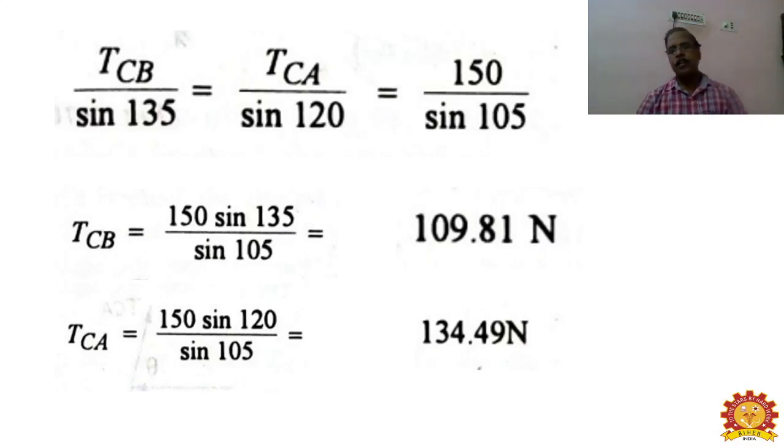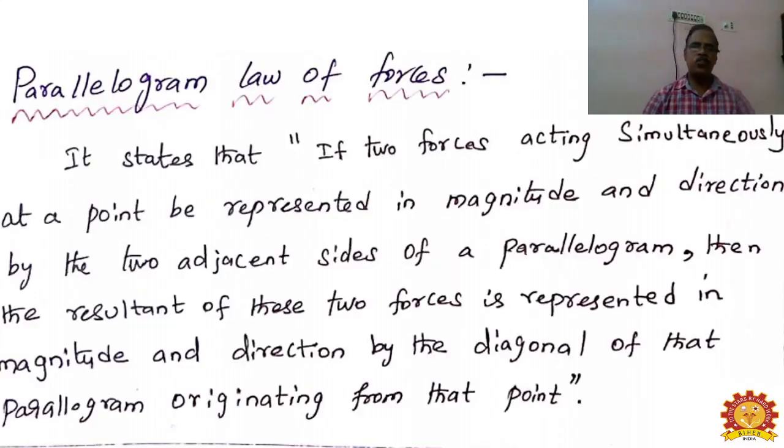the Lamy's theorem. Now let us go to one more equation which is called the Parallelogram Law of Forces. It states that if two forces acting simultaneously at a point be represented in magnitude and direction by the two adjacent sides of a parallelogram, then the resultant of the two forces is represented in magnitude and direction by the diagonal of that parallelogram originating from the point. Maybe a little bit confusing because it's a lengthier one.